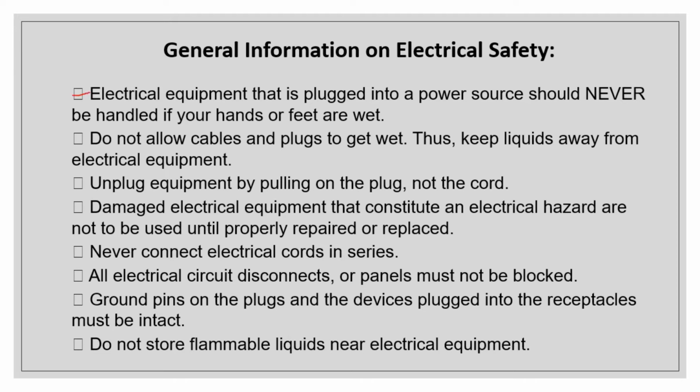Electrical equipment that is plugged into a power source should never be handled if your hands or feet are wet. Do not allow cables and plugs to get wet. Thus, keep liquids away from electrical components. Unplug equipment by pulling on the plug, not the cord. Damaged electrical equipment that constitutes an electrical hazard is not to be used until properly repaired or replaced.